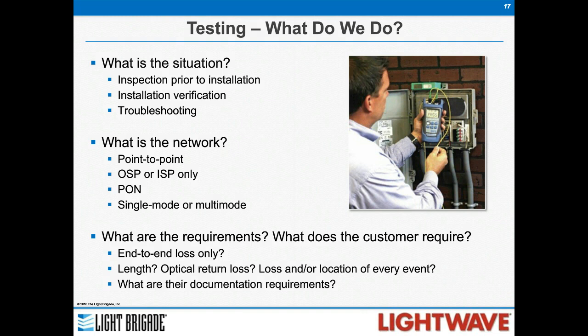Are you doing installation verification? So you've already pulled in all your cable, you've connected your patch panels or whatever's in your network, and now you need to verify that you meet your losses. Or are you going out to troubleshoot? Because depending on what you're doing, you may need different tools in your tool bag.